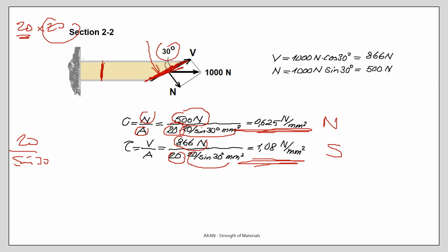As you see, when you have a point like this, depending on how you cut, you can cut like this, like that, or like we did with 30 degrees. So if you tell me that you know the stress state at this point P, you must be able to calculate the stresses on any plane passing through that point.